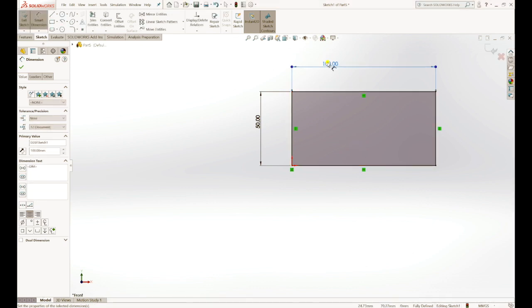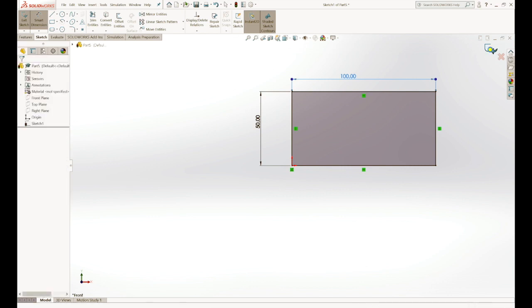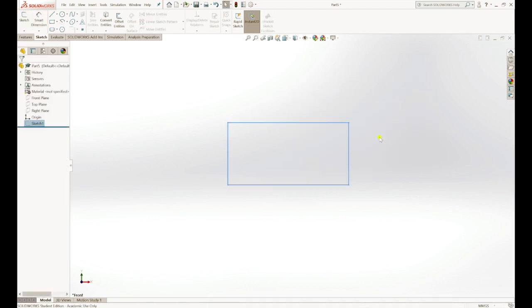So this is very useful in SolidWorks. Every time you have to type a dimension or a number, you can do some calculations, or even convert units. For example, if you want to use inches, you just type, for example, 2 in, and it becomes converted to millimeters automatically. It's quite useful. Once I do that, I just press OK, and now I have a simple rectangle.